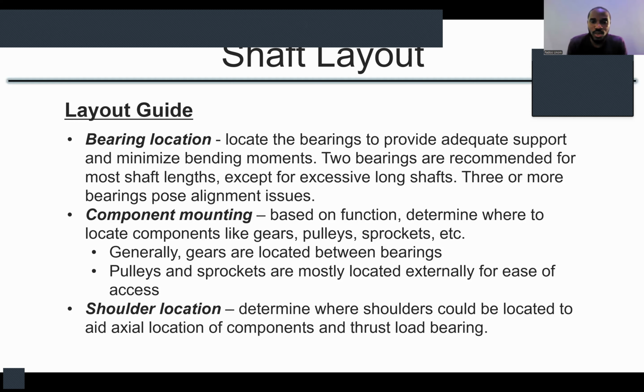Okay? So use 2 bearings as much as possible. When you have very long shafts, then you can use 3 or more, but you must ensure that you align them properly. And it's always very, very difficult to align shafts. Okay. So that's bearings. And I will show you a little bit.